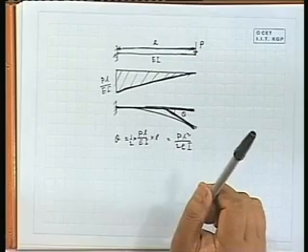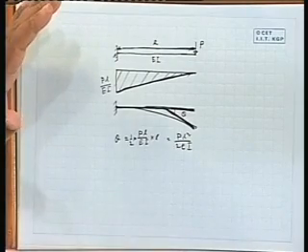And here one of the advantages is that one of the supports is fixed. So, as it is fixed, one of the tangent lines is the initial line, that is a great benefit here. Okay. Earlier we took a simply supported type of beam, where the first slope and last slope are not the original line. Okay. Here the advantage is at the left end, the tangent is the initial line. Okay. So, if you draw the tangent at any point here, that will be the effective slope. So, straight away we can calculate.